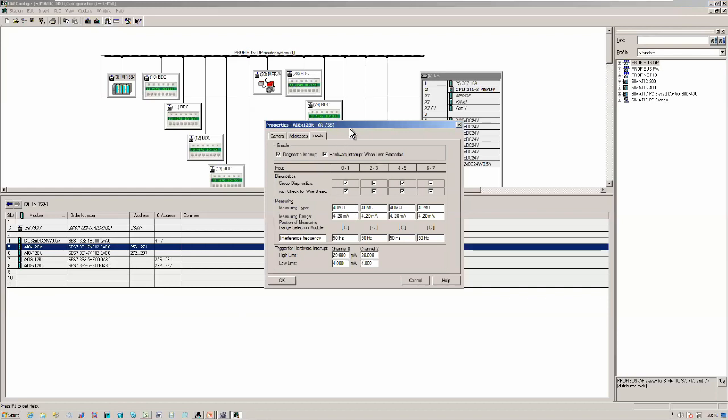On this S7, you can assign per 4 channels what input it is, whether it's a 4 to 20 or a 0 to 10, etc. You can change it in the config here. You see this little letter down here, the C. There's a block on the back of the analog input card that can go in a direction A, B, C, or D. It has a little arrow on it, and you have to turn it to point the arrow at C, and then the analog wiring inside the block will work as a 4 to 20.